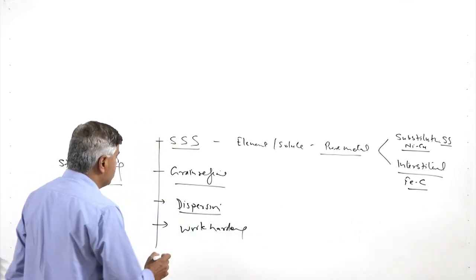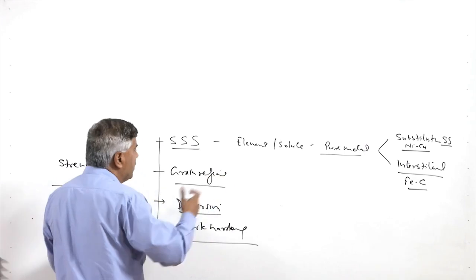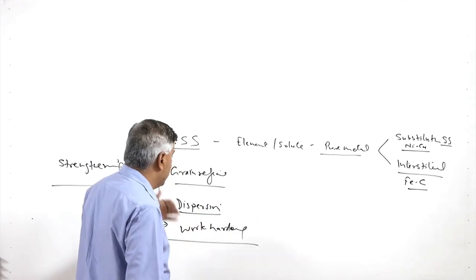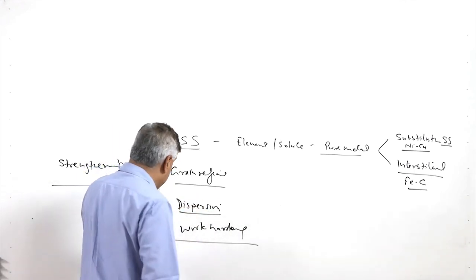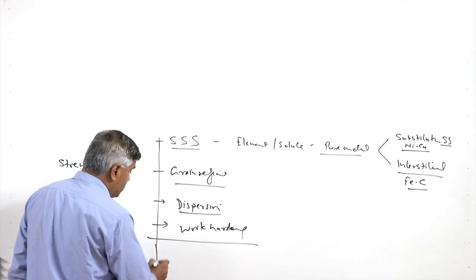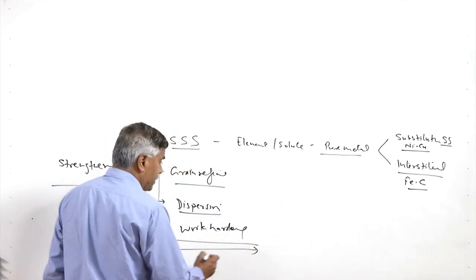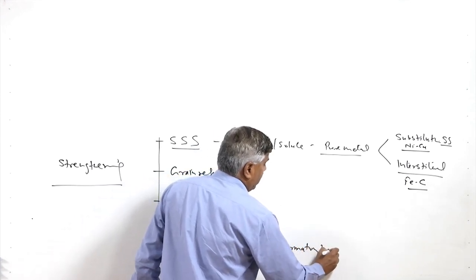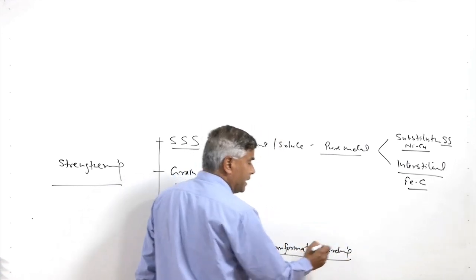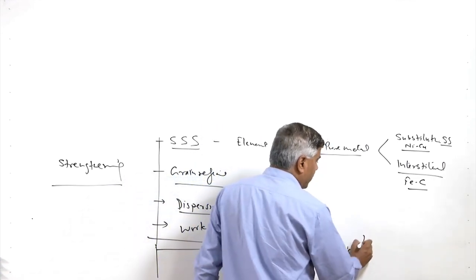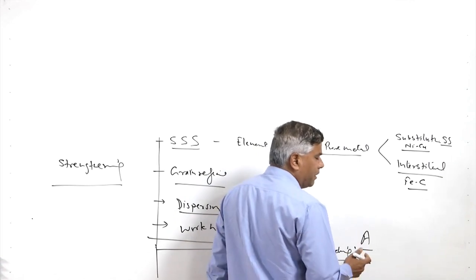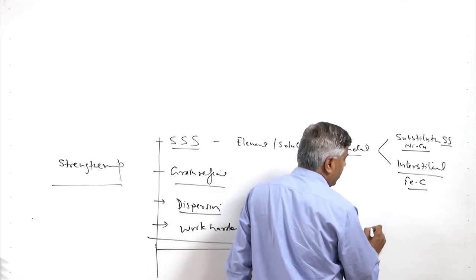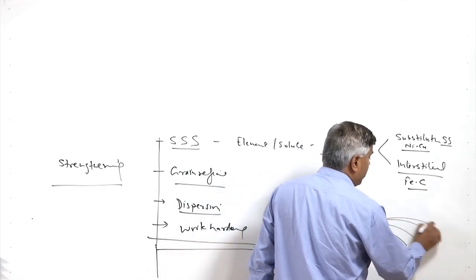So, these are the mechanisms which use different approaches like alloying, refinement, reinforcing with hard particles, or plastic deformation. Now, the two approaches about which we will be talking are related to heat treatment. The first is transformation hardening. This is typically used for the heat treatment of steels, where one phase like austenite, which is stable at high temperature, is unstable at room temperature conditions. So, using different cooling rates, efforts are made to get different kinds of phases, so we get different properties.